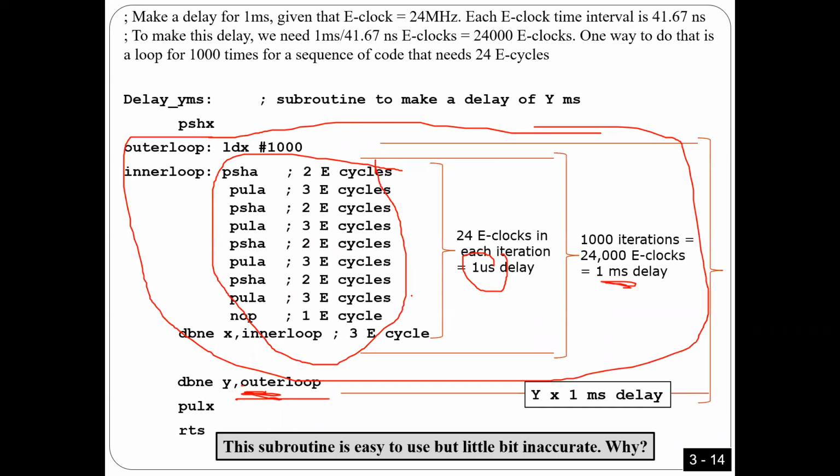I do some instructions that are not doing anything useful. I'm just wasting time. Push, pull. But the time needed to execute these instructions from here to here is actually 1 millisecond. And then I repeat it Y times. That's how I can make a Y millisecond delay.